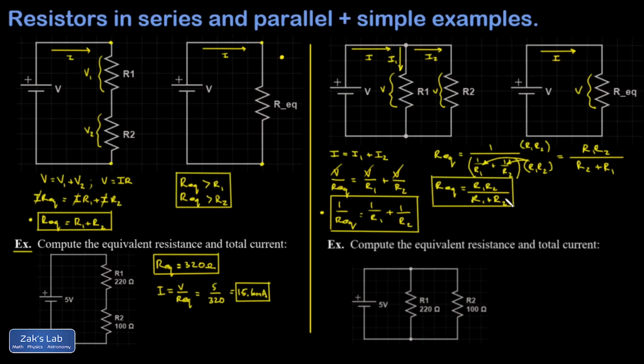And now I'm going to find my comparisons with the original resistors. And the idea is this. I can say that Req is definitely less than R1 R2 over R1, because R1 R2 over R1 has a smaller denominator than R1 R2 over R1 plus R2. So I just removed R2 from it, made the denominator smaller. It must be a larger quantity. So now it's bigger than Req.